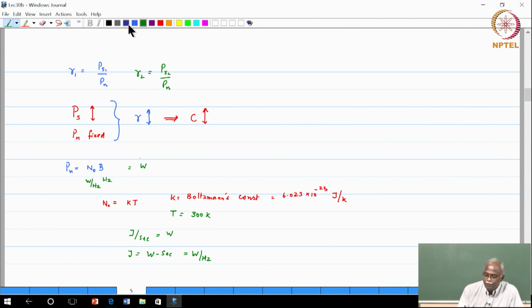So, the noise power Pn in general for any receiver is calculated as K times T times B, and sometimes we make it a little easier just by specifying N naught, but you do not need to do that. You can actually compute what the noise floor is and then calculate the noise power, and this is how it is done. Okay. So, at the end of the day, what we are interested in is the fact that the SNR is fluctuating, and therefore capacity is fluctuating. So, it is a challenge for us in terms of achieving what we want to achieve.